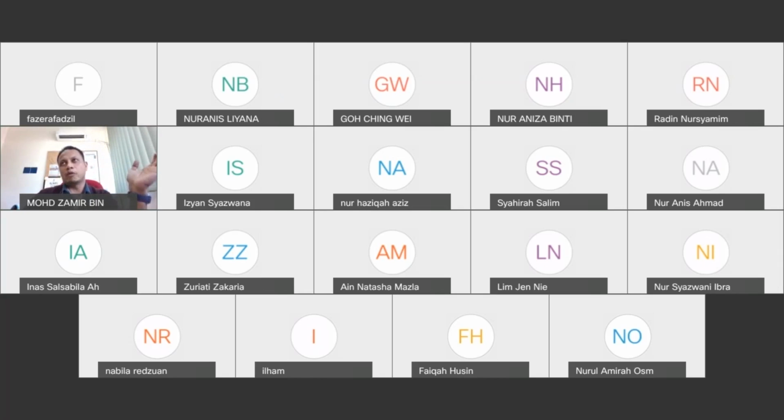So it depends on where is the root cause of the problem. So if the root cause comes from the oxidation process, step number X, then the yield engineer has to follow up with the process engineer of oxidation, step number X, in equipment Y, to be able to get the problem solved. So you can even go with the process engineer, equipment engineer into the fab and looking at what they are doing to actually solve the problem, to, I don't know, change parts or change process parameters and rerun and prove that the defects are gone. Okay, but you don't really press buttons and change here and there to get problem solved, but you work with somebody else. So in this case, process engineers or equipment engineers.